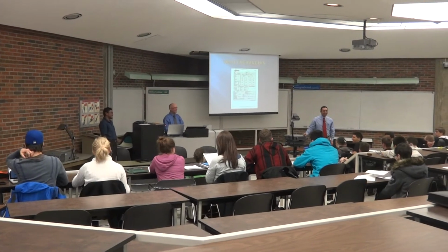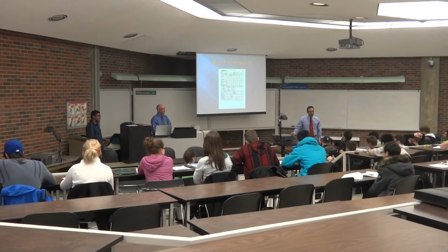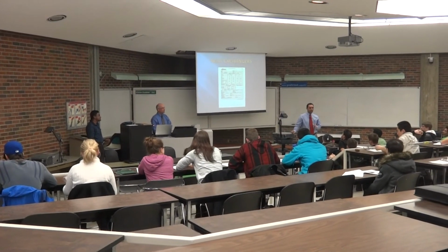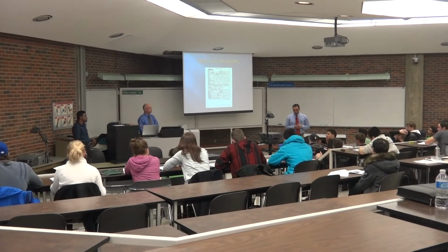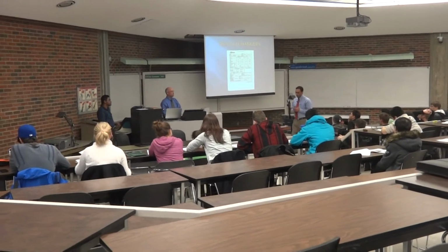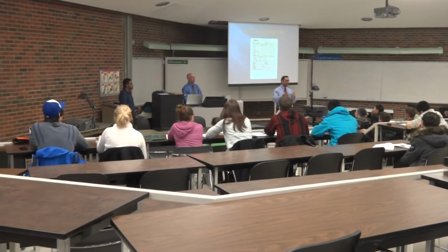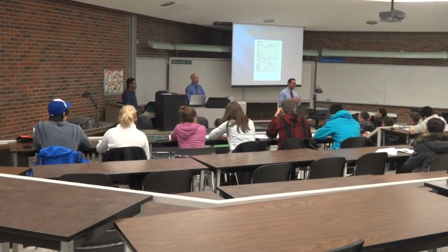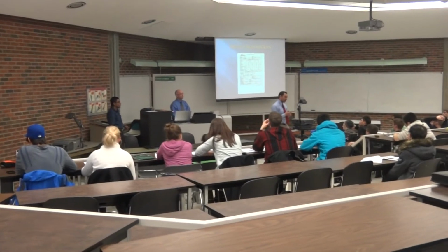On the shell side, I know that there's a number of these pieces. Those are called baffles. How do you program those? There is a TEMA requirement. You have to be within 48 inches, the maximum spacing you can go. You can go up to 60 inches, but the maximum recommended is 48, because after that you start having vibration issues.